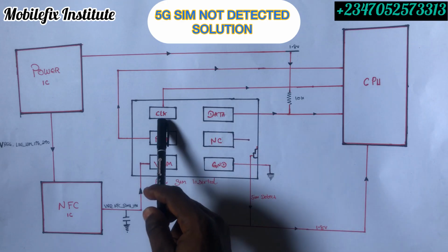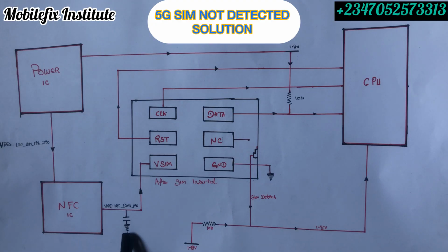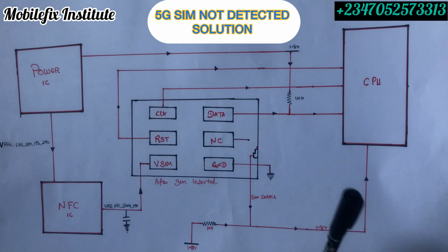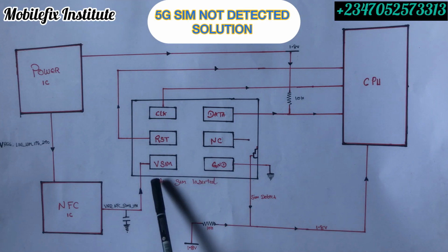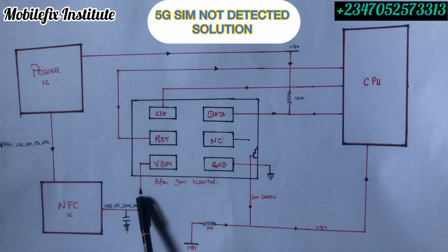The same thing is applicable to this clock and this VSIM, voltage for SIM. Here, I put a capacitor. So any of these pins can have a short circuit. If you realize that any of these pins is shorting, you have to trace the line that is connected with this pin.